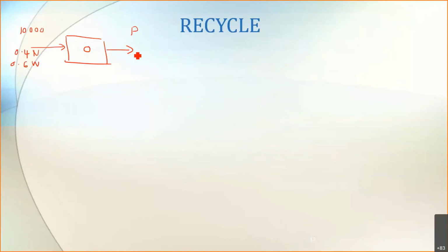This is my product where I have 0.95 NaOH flake, our crystal or filter cake, and then 0.05 NaOH solution, which contains 0.45 NaOH and the rest, 0.55, water. And then I also have water that is evaporated, so I can put here W.